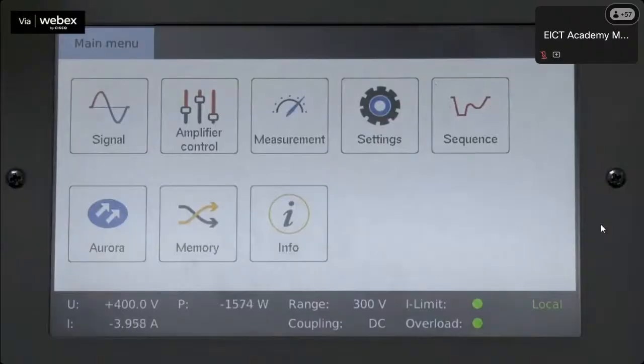The power amplifier power sign is negative, which means the power is flowing from the AC grid to the DC bus. So, earlier it was DC bus to AC grid, and now it is AC grid to DC bus. The DC bus voltage is always regulated to 400 volts. From these test cases, we have witnessed the energy exchange between the AC grid and the DC microgrid.